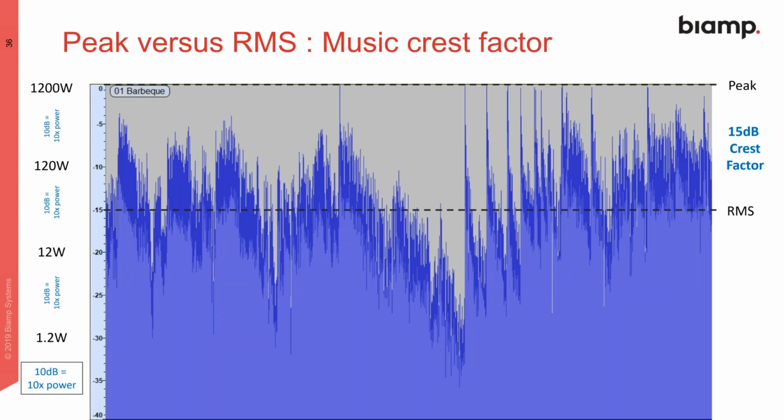Now we would have to apply that to our speaker and look at the sensitivity of the speaker to find out how loud that speaker is going to play out in the space. If I've got a very inefficient speaker, it's going to be quieter than a very efficient one. A horn-loaded driver is going to be more efficient. It's going to put out more acoustic energy for a watt into it than a ceiling speaker, which can be fairly inefficient.